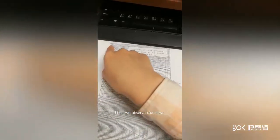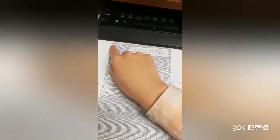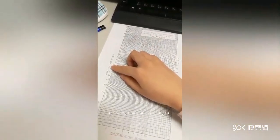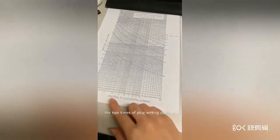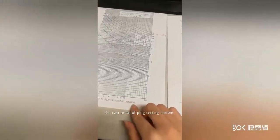Then we go to the curve, and find the y-coordinate is 10 seconds. So 10 seconds is the normal operating time for 2 times the plug setting current.